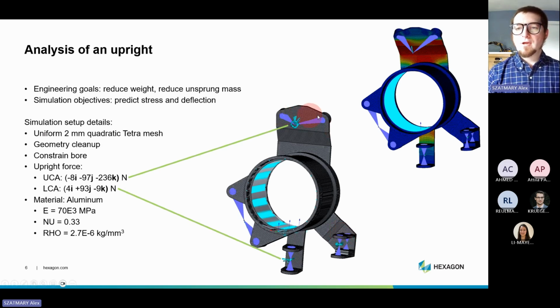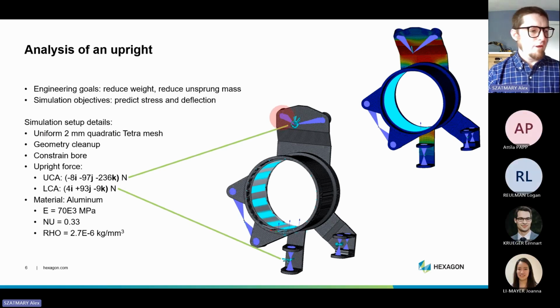Up here, we're not actually showing the direct attachment point for the upper control arm or its bolt. That's something that would be held on by an additional bracket, and then that bracket would relay loads. And for our purposes, it's going to be a fine assumption to suppose that those loads are being transmitted through these two bolt holes up here.